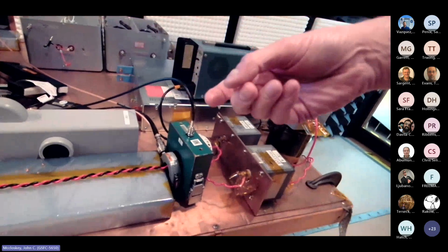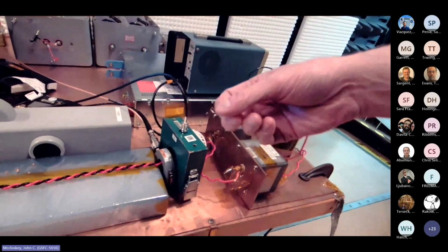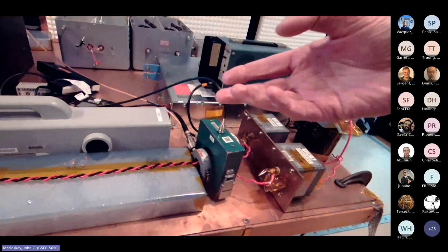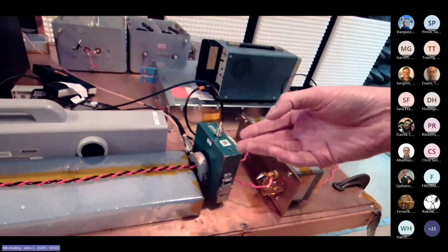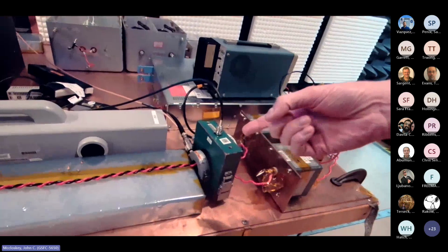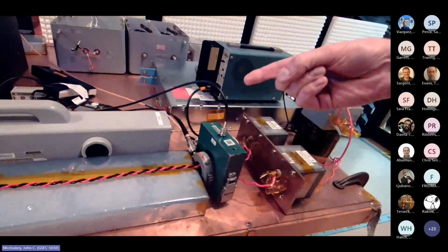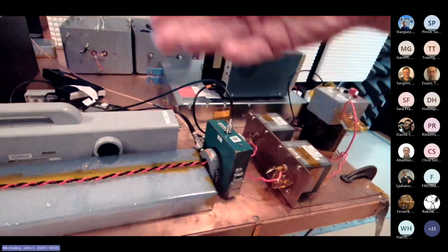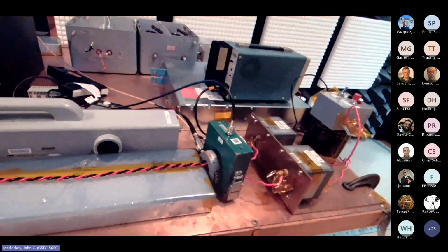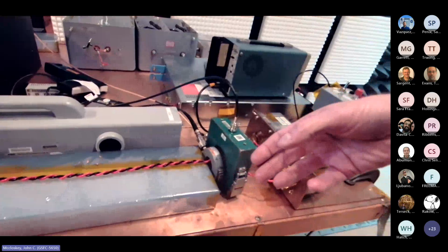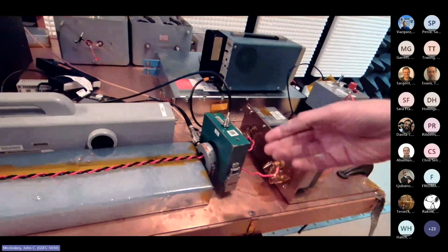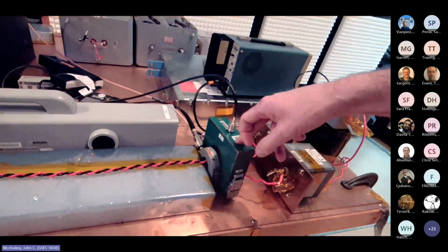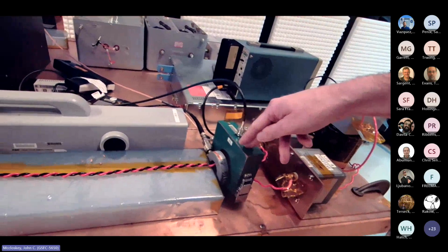It's half that into a 50 ohm load, but I like to use it into the 1 megohm load of a scope, because then the math is very easy. Then it's 100 millivolts per amp, or the other way to look at it, 10 amps per volt. We're going to be looking at millivolts here, or milliamps, so it's like 10 milliamps per millivolt. The frequency range of operation is 10 hertz to 10 megahertz.